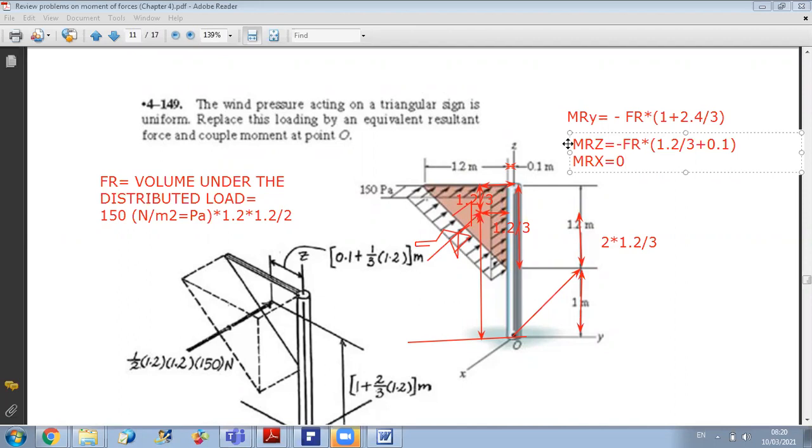Because if I want to draw it on my figure, the vector moment will have a negative y, negative z component. So if this is the yz plane, and this is z, okay? Then my moment vector will have negative z, negative y component. So this is my resulting moment, let's say, okay? And I can find the angle here by just doing tangent minus 1 of FrZ over FrY. Okay, so let us look together at the solution briefly.